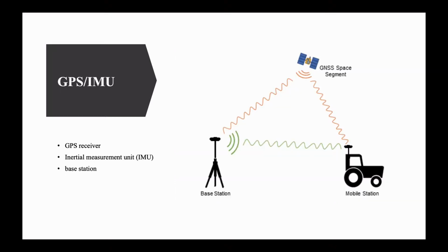The positioning system mainly consists of a navigation and positioning satellite position receiver, such as a GPS receiver, and an inertial measurement unit, base station, etc. The GNSS board card receives signals from all visible GPS satellites and real-time kinematics via antenna, and then interprets and calculates its own spatial position. GPS provides more accurate location information with low update frequency, while IMU provides relatively low accuracy location information with high update frequency.